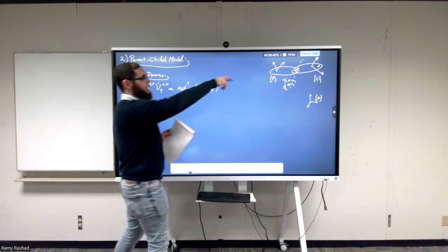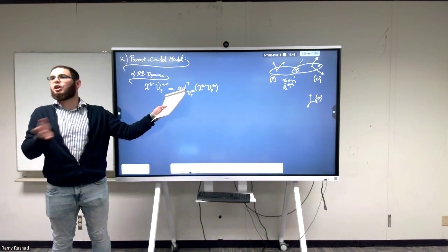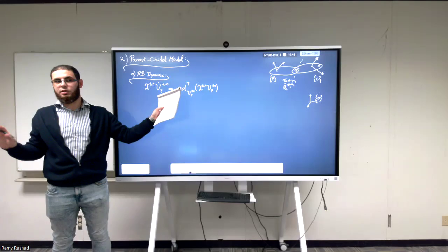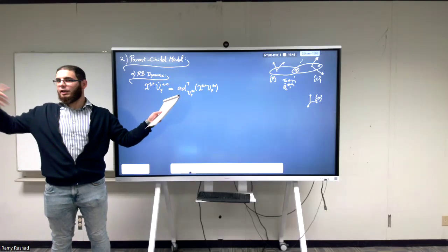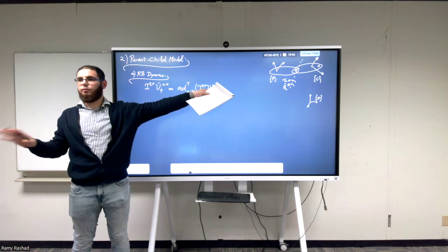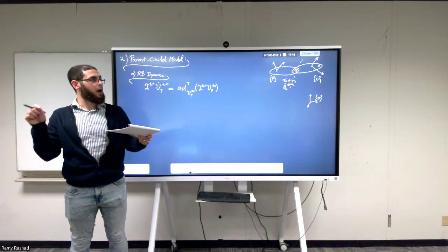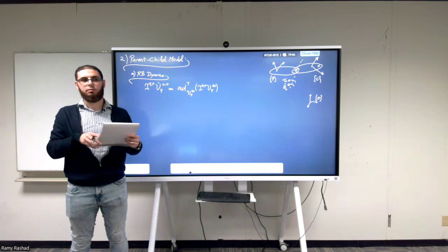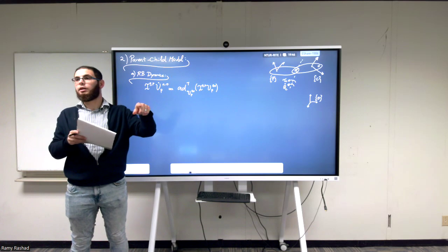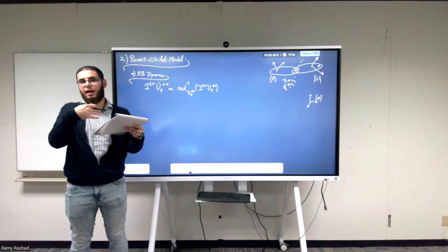And then what are the external wrenches applied here? This equation simply says that the rate of change of the spatial momentum is equal to 0, so momentum is conserved. If we have external wrenches, then we get them here. Let's assume there is no gravity for the time being. What is the only wrench that's applied on the parent body? Due to the child, right? If the child starts to move around, it will push the parent body.